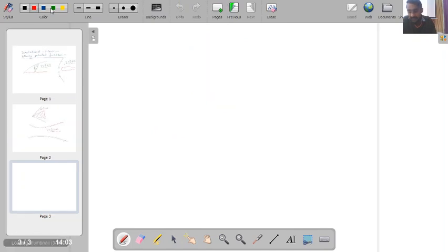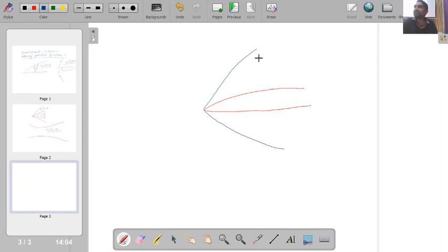Similarly, I have told you earlier also, if I take very slender objects, an object with a sharp tip that is very thin, its thickness is small and length is long, then in this type of situation I will have a wave which will have slight curvature, however the strength of the wave will not be that much different. So though here the curl of V will not be exactly equal to 0, it can be approximated as nearly equal to 0. So if we have slender objects with sharp tips, for these also we can apply the irrotational flow theories.